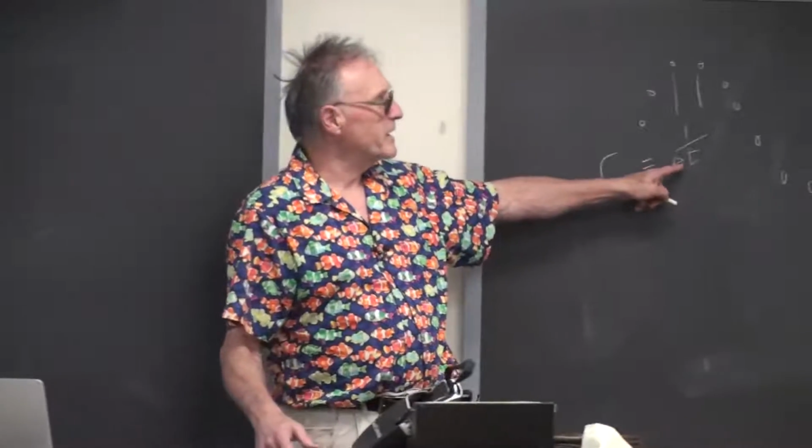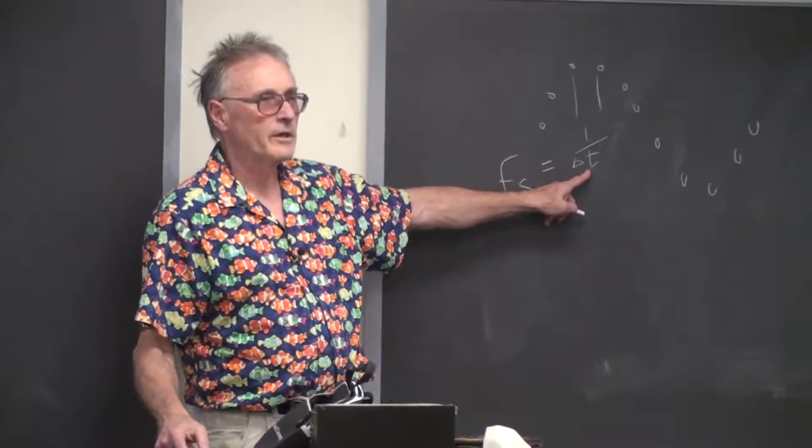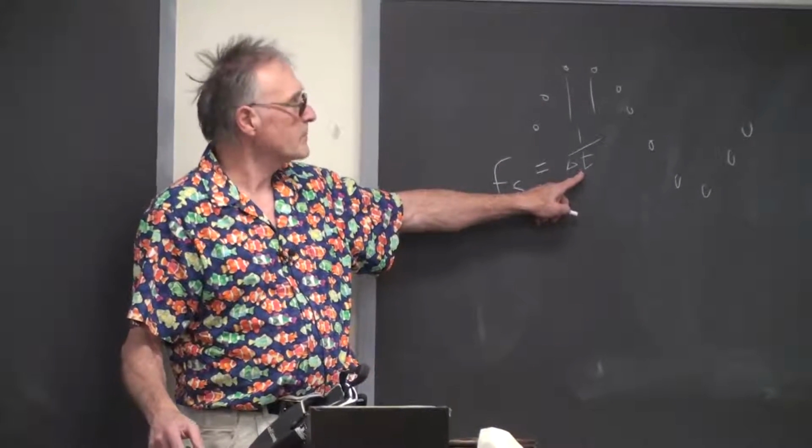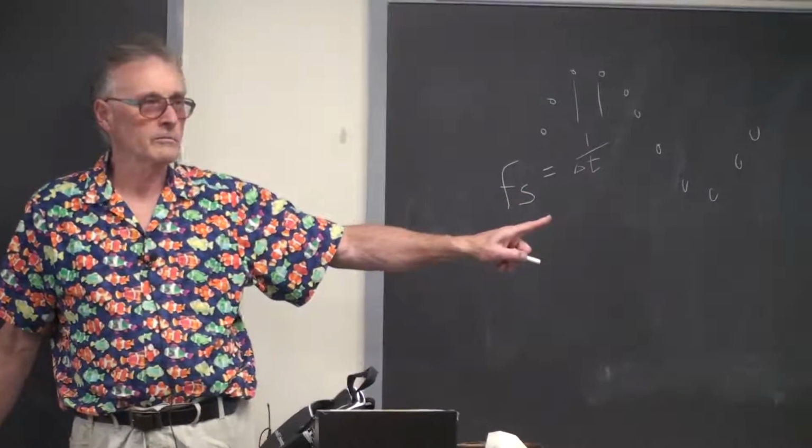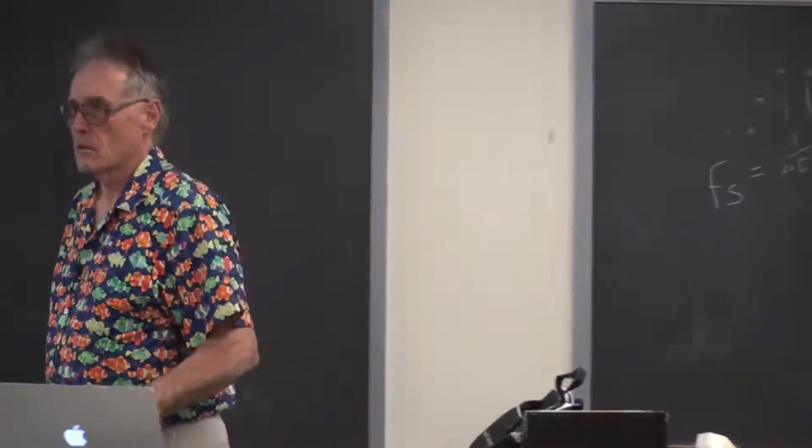What do I mean by too long? If the interrupt service routine takes more than delta t to execute, you're in deep kimchi. It won't work, because it'll take longer to execute than the time between samples.